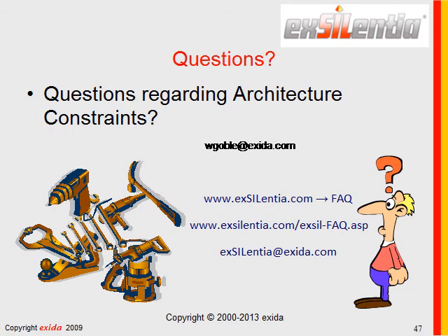It gives you the best of both worlds: full confidence based on history of field failure data and certified design processes to protect against systematic integrity. So I like to think that many of the certified products that have both 61508 certification and Route 2H compliance are really presenting a set of evidence that's stronger than any other, that they are suitable for safety.